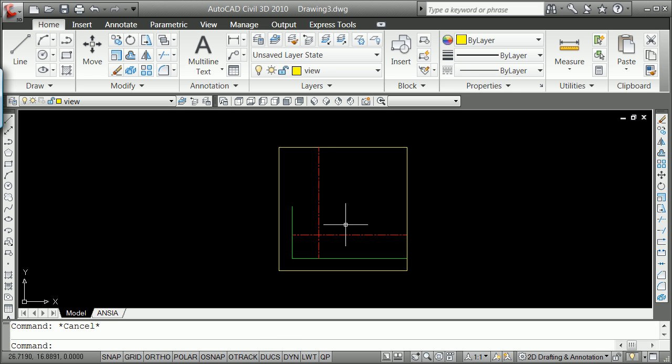There'll be other ways, the length command, lots of others. Let me finally show you first time through how I'm going to make that change. I'm going to left click now. I've got the dynamic off. I'm going to left click on top of something. I'm going to hit space bar, C for copy, and I'm going to change it 31 degrees, turning it to the left, which is a positive angle, and I've got the next step there.